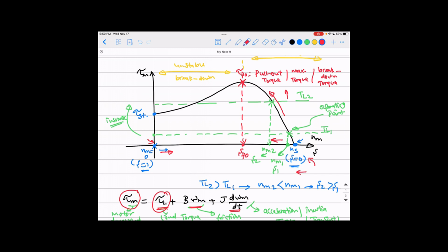Until you just hit this point. But after this, the torque will start decreasing and the speed will also decrease. That's what we call breakdown. The machine is losing torque and losing speed because you're in a breakdown. The winding will start burning. That's why we don't deal with this as an actual zone, because you don't really go in there much, otherwise you're burning your machine. So most of the time we're just dealing with this area, the stable zone of the machine.